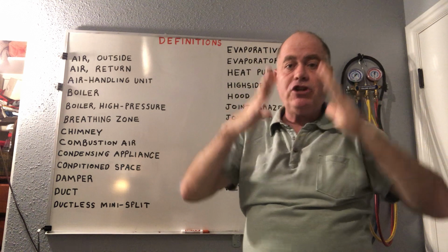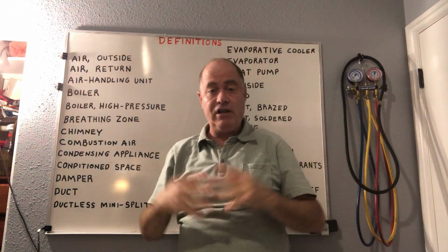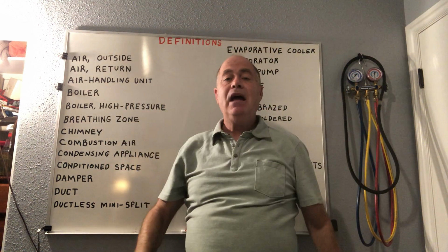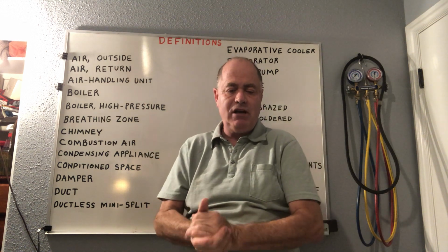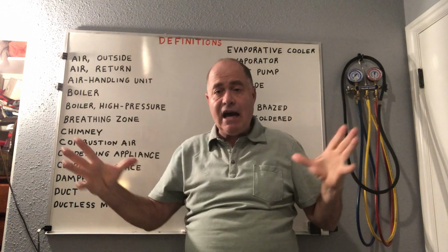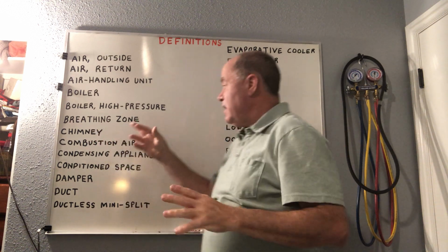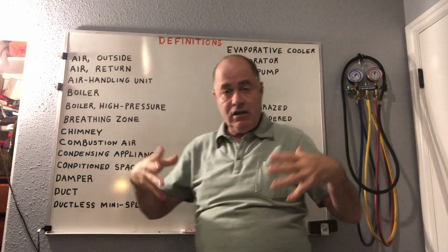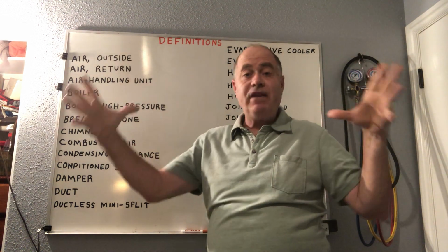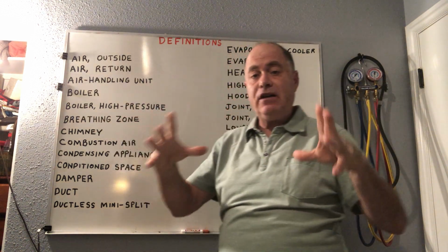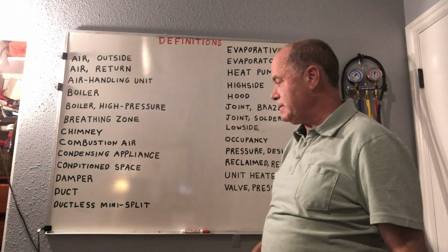That would be dilution air on top of your hot water heater. That air can leak in and dilute the products of combustion, mainly lowering the relative humidity. And also, part of combustion air is just to have some ventilation, to dissipate heat and things around the heating appliance.